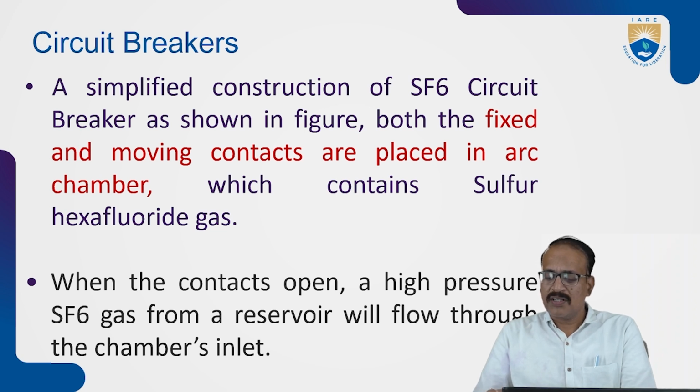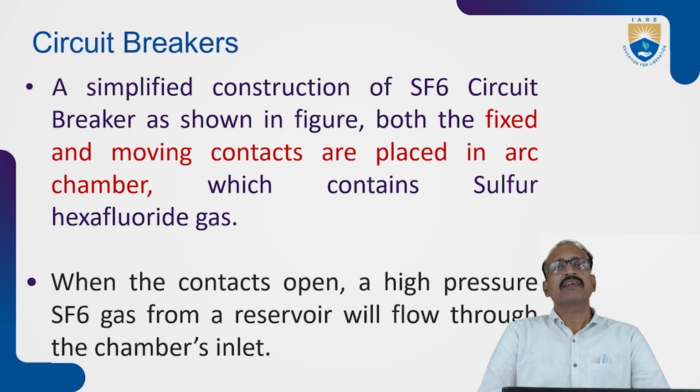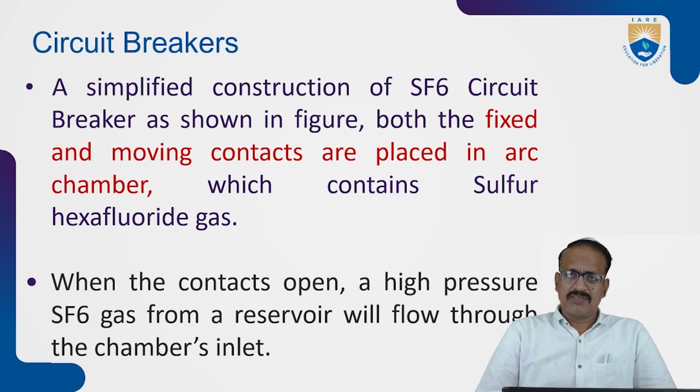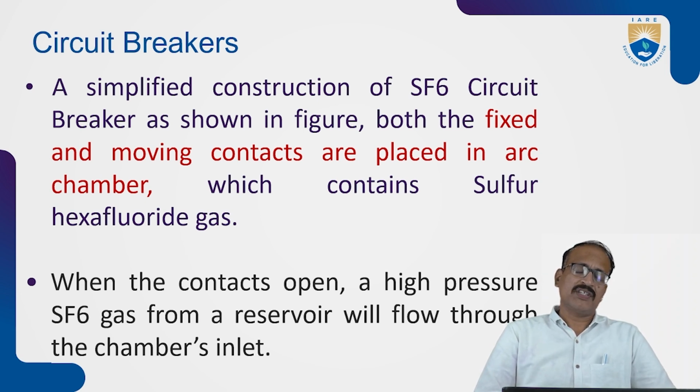Here also there will be a moving contact and a fixed contact, and whenever the contacts open, there will be some ions, and because of this the arc exists. The arc cannot be extinguished immediately; it will take time. How fast we can extinguish it is what matters.